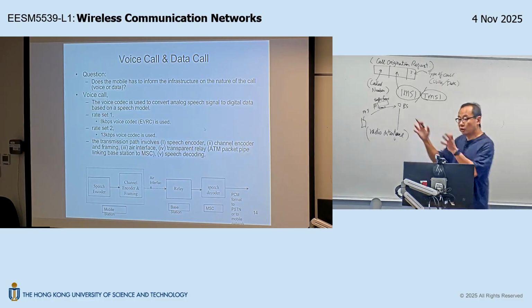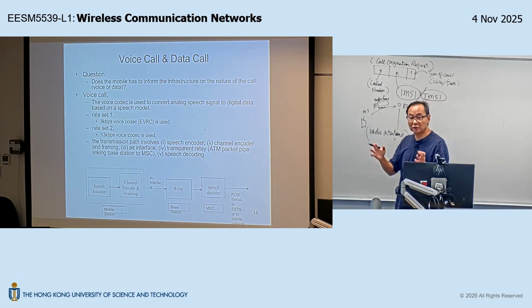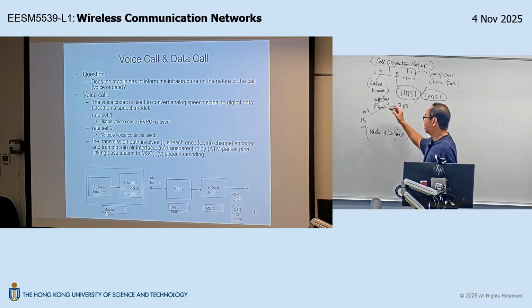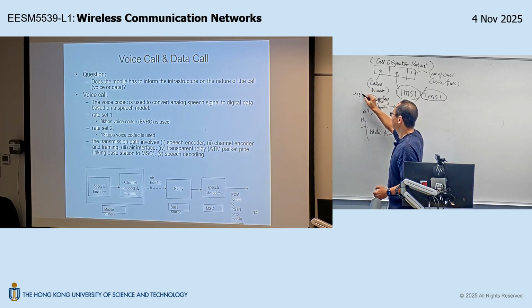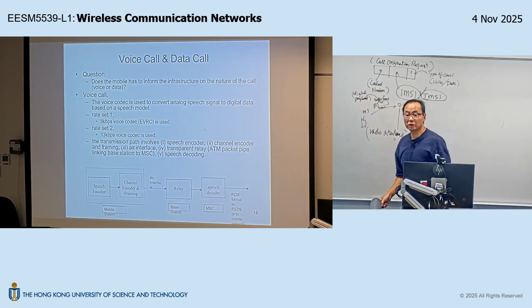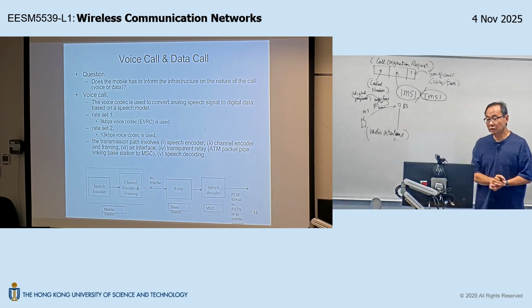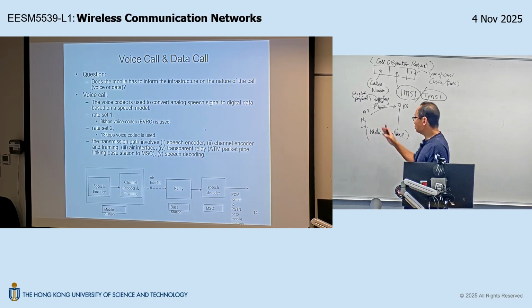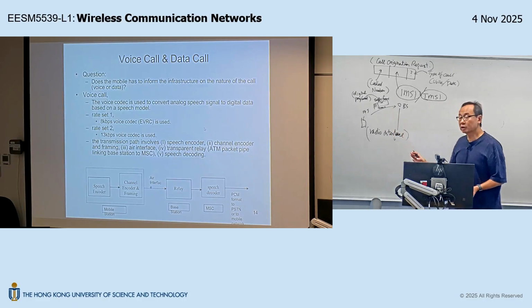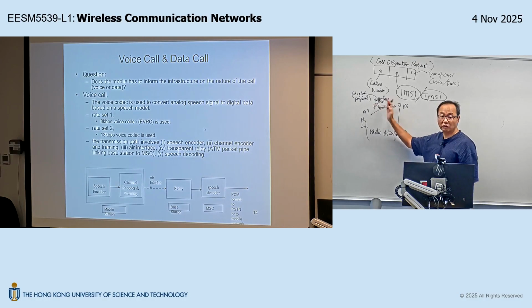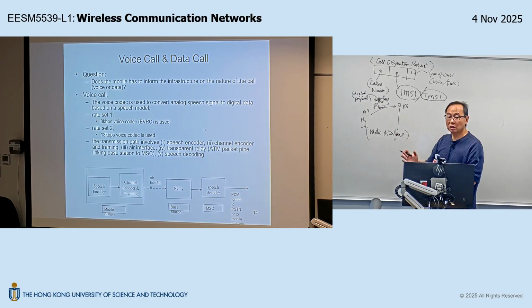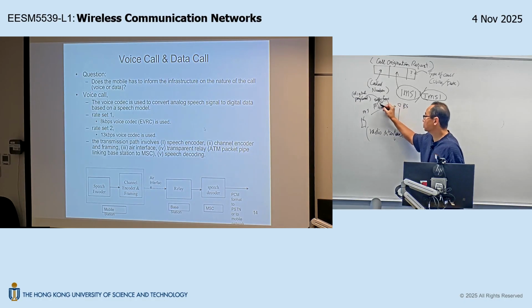You can think of this traffic frame as a bus. So every traffic frame can carry some digital passengers. We call this digital payload. Let's say a number of bits, let's say 300 bits. Now, as the digital cellular interface, the radio interface will be able to deliver every frame, every bus, let's say, 300 bits, 300 passengers.